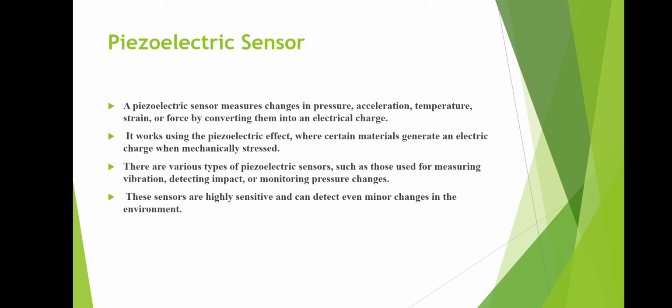Then piezoelectric sensors. Piezoelectric sensors measure change in pressure, acceleration, temperature, strain or force, converting them into an electrical charge. The piezoelectric sensor works on the piezoelectric effect, where certain materials generate an electric charge when mechanically stressed. There are various uses of piezoelectric sensors such as measuring vibration, detecting impact or monitoring pressure changes. Piezoelectric sensors are highly sensitive and can detect even minor changes in the environment.